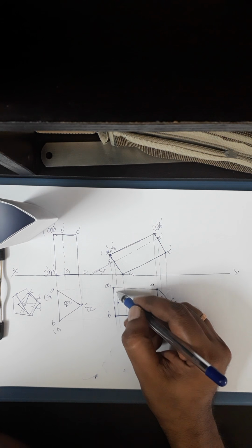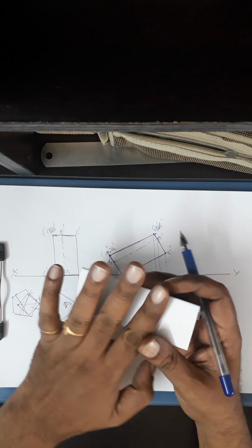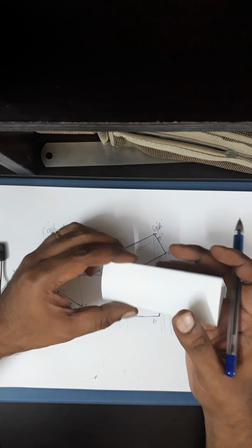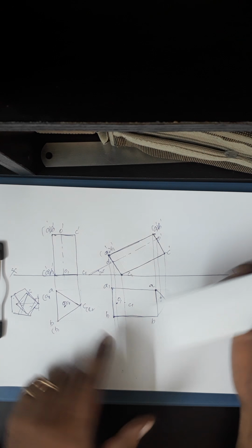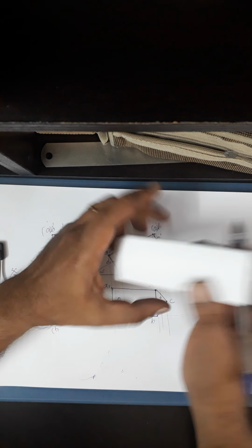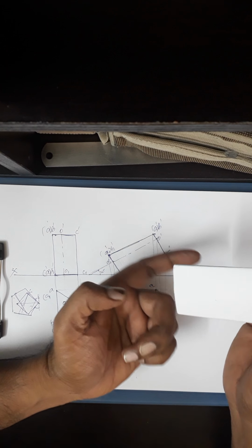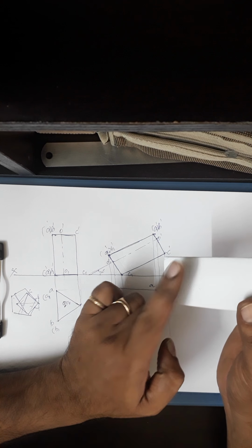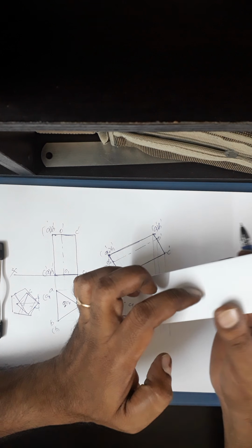So I cannot have any line on the surface, okay. That should be a plane figure, right. So in that case, all these edges which are not joined now, A1, C1, B1, C1, okay, all that should be a dotted line. So that becomes invisible edges. That's why you can see only the surface here. So that will be exactly below that, okay. In that way I cannot see that, so that becomes invisible edges, even that C1 also.